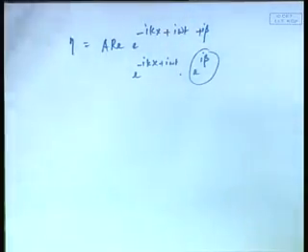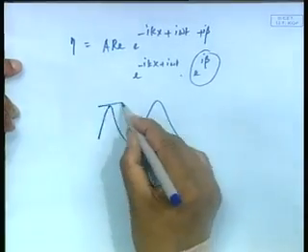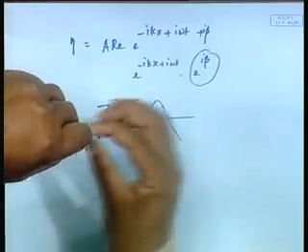Now, this is very important, because in water wave mechanics and in the floating body response subsequently, things do not occur at the same time, the peak values all. If something happens highest now, something may be lagging behind it. I want to give you this example. If you look at my hand, supposing I twist my hand, you will see that this tip point goes this way, but this point may not exactly follow that. If this is having a peak here, you will find that my this one is actually reaching later.